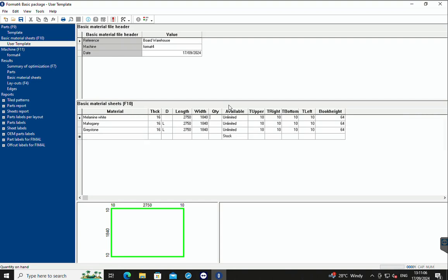And if you use a board, Ardis will automatically deduct the boards from your quantity you added. It's a lot more maintenance to do, nice to have, but what we normally recommend for customers is availability. Just type in unlimited and it won't calculate any boards, it will just generate boards.